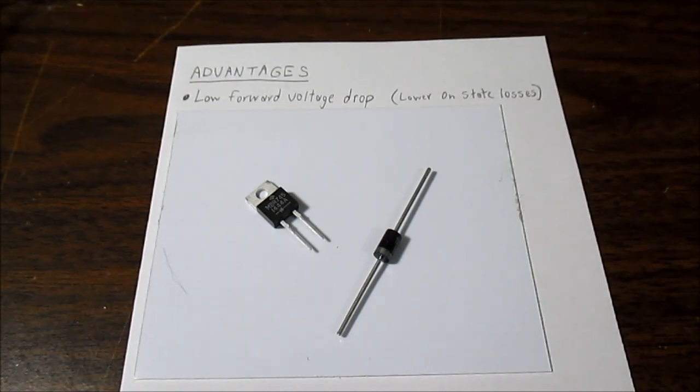If you take an ordinary PN junction silicon diode, apply a forward bias to it, it will not start conducting until you reach around 700 millivolts, give or take, depending on the current. And that could be a source of power loss. For example, let's say you have 3 amps current passing through the diode and it has the 700 millivolt drop across it. Well, the diode's going to dissipate a little over 2 watts. So, that's a significant loss of power right there.